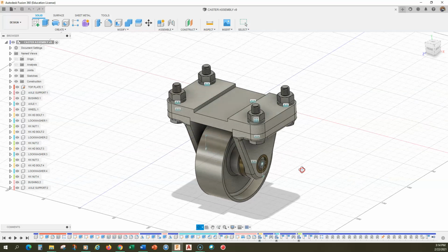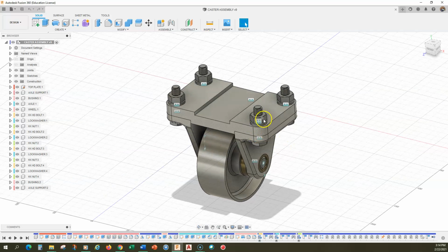We wouldn't have a detailed drawing of the nut, bolt, and washer, because those are purchased parts. And then we would also have a drawing of the assembly showing everything. That's called a working drawing set, when you have all those drawings together so that you can manufacture each part and assemble them.